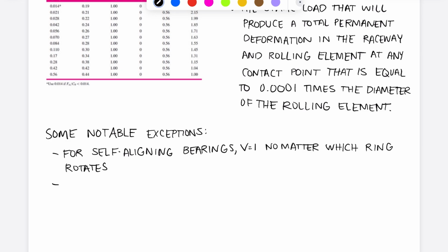And straight or cylindrical roller bearings are going to take little to no axial load, so Y will always be equal to 0. In other words, the straight and cylindrical roller bearings that don't take any axial load will not have an equivalent radial load that is affected by that axial or thrust load.